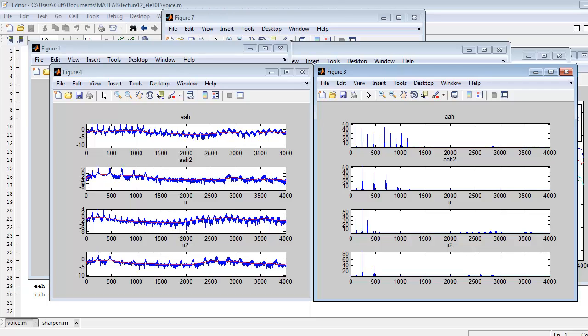I don't love this trick, but it's very common. It's called cepstral coefficients and so forth. If you work in speech, you'll come across this. Really what they're trying to do is pull out the envelope of these harmonics. And this just turns out to be a very brute force, simple way to do it, where you just do a low-pass filter of the log of the spectrum. Okay, but look at what happens when I do that. This red represents the low-pass filtering. The red is then going to be interpreted as the frequency response of my mouth and throat when I said that sound.